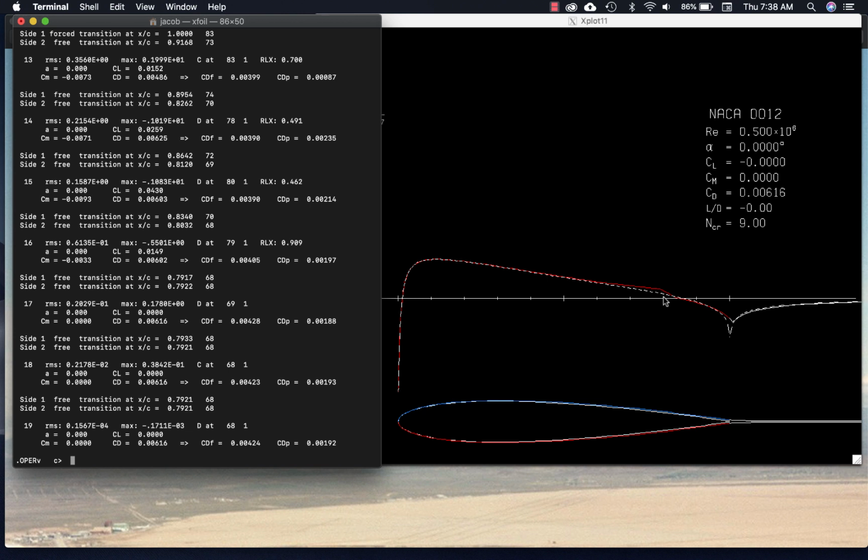So let's say we stick with that 100 feet per second flow velocity. If this were a 1 foot airfoil, then that transition location, we run that calculation for a critical Reynolds number of 500,000, is going to be around 3/4 of a foot, give or take, and you can run the detailed numbers on that. If you scale or take a larger airfoil, let's say 10 feet, for that same critical Reynolds number of 500,000, it's still going to be 3/4 of a foot, because that Re_c is telling you where that flow is transitioning.